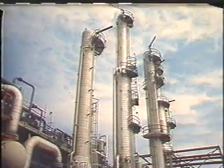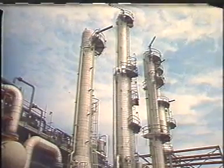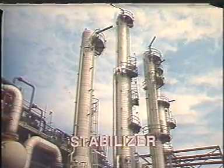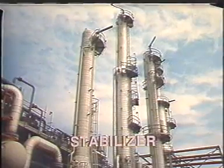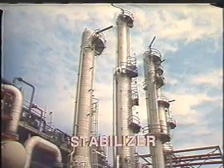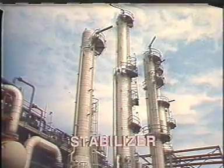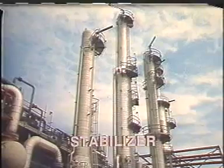The liquid product from the separator is sent to a stabilizer. The purpose of stabilization is to separate out light hydrocarbon gases that were created by the reforming reactions. The product drawn from the bottom of this vessel is the stabilized reformate.